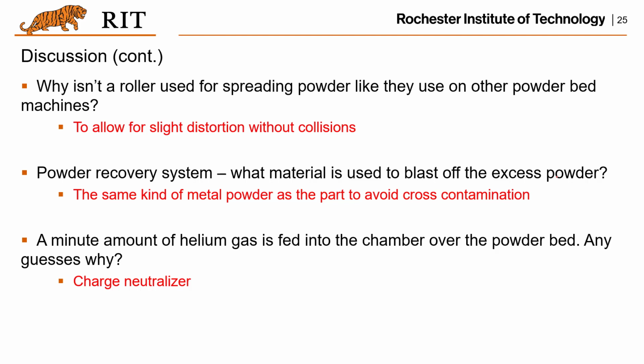And also, there will be a small amount of helium gas fed into the chamber over the powder bed. Of course, if you have some helium gas there, the electron beam could hit the molecules of the helium. But that's a minor effect, because the amount of helium is really small.